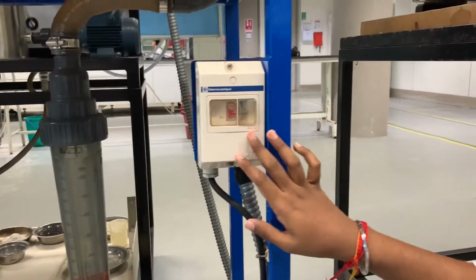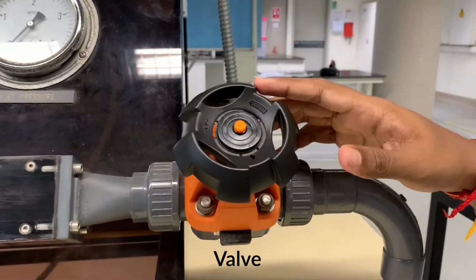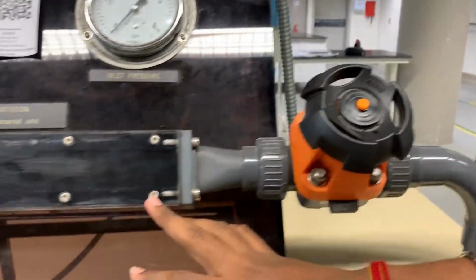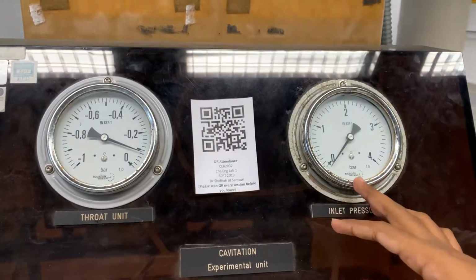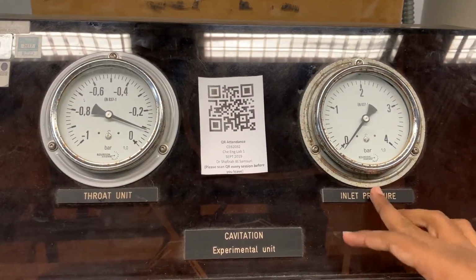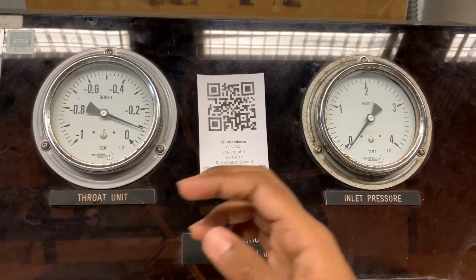Next is the switch for powering it on and off. This is the valve. The valve is used to regulate the flow rate, and here is the venturi meter. There are two meters. The first meter is the inlet pressure indicator, which is P1, and this is the throat pressure indicator, which is P2.